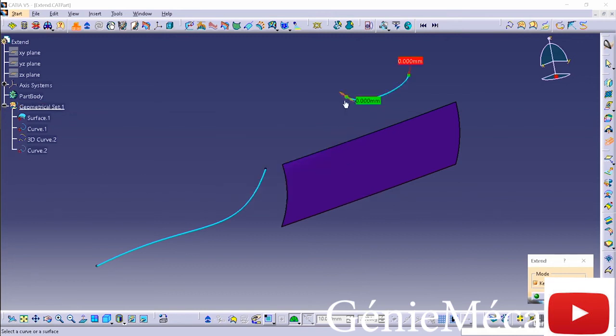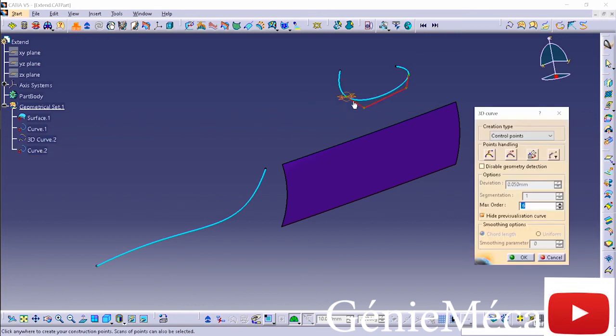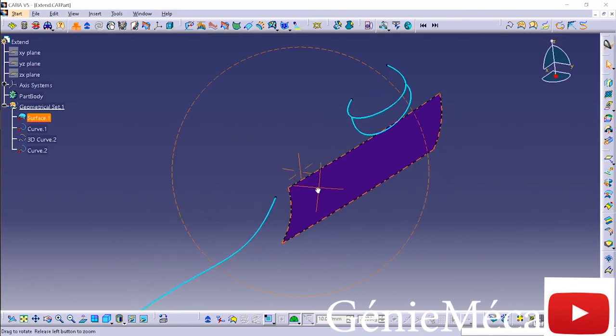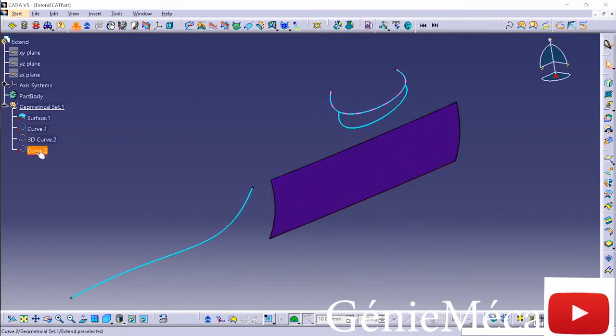So I'll select OK, drag this out, select OK again, and here's that 2D curve. If I were to make a modification to this 3D curve, you can see that there's no historical link, no updates, no nothing back to it, because the new curve that's generated off of it basically copies it, takes that math, and makes it a non-parametric or unlinked copy.